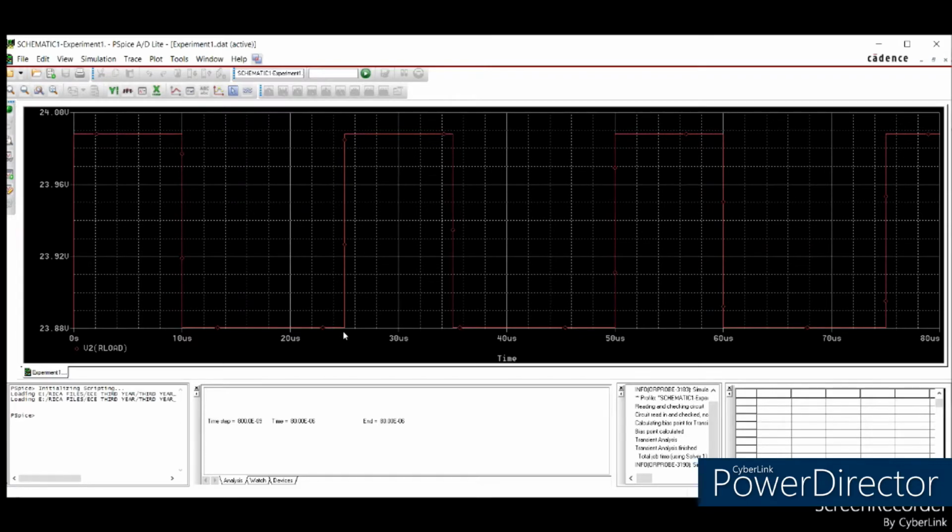Same with our control switch voltage, meaning the two pulse waveforms are in phase with each other since their period is similar as well as their pulse width. Same analogy, taking note of our almost 24 volts peak voltage here. The voltage is applied here when we had our peak value, and then it will be off here up until it reaches its 25 microseconds period, wherein it will repeat one cycle all over again. This waveform process will repeat for the time duration we set on our simulation settings. So that's our part 1.